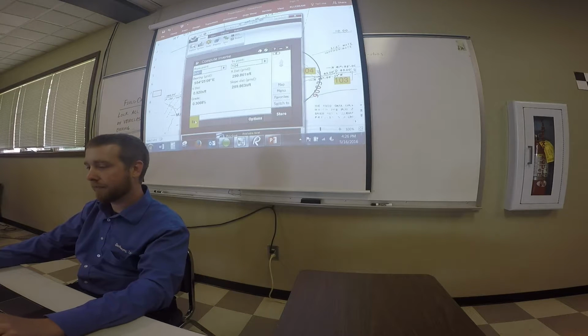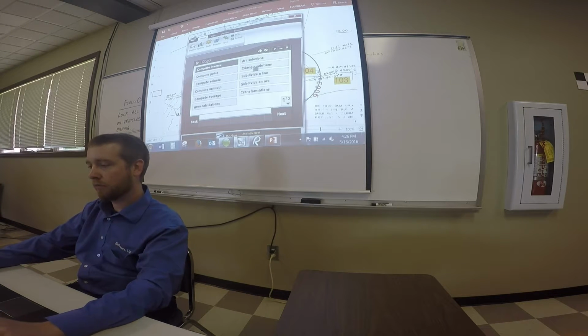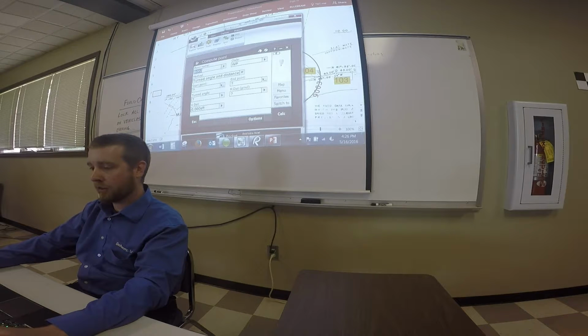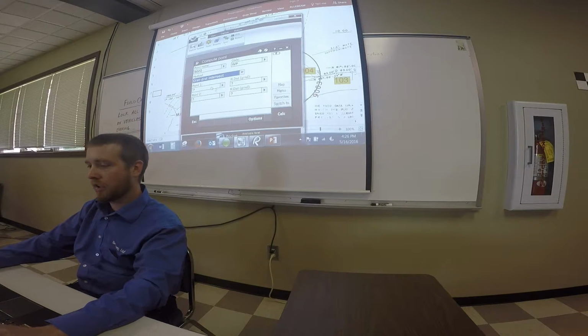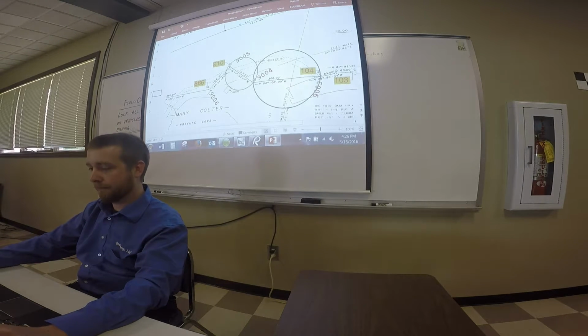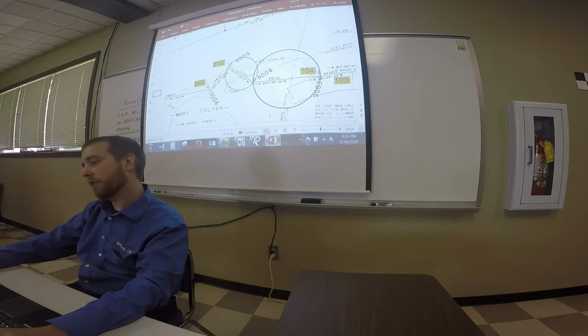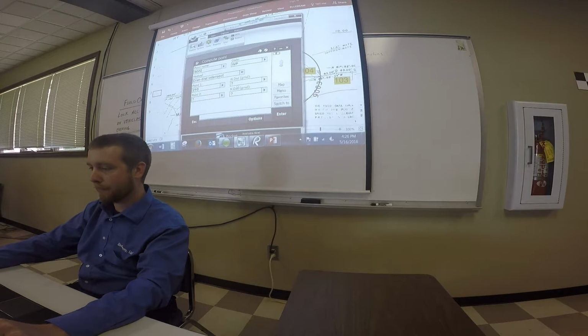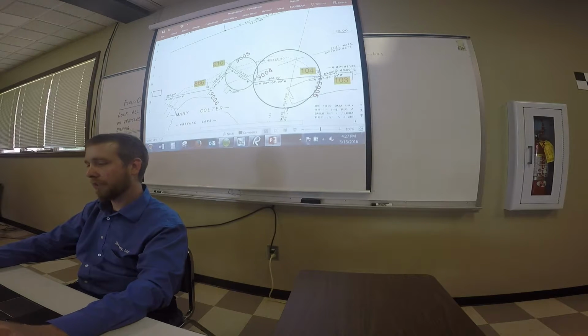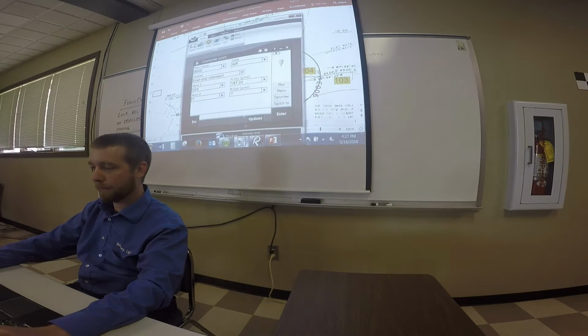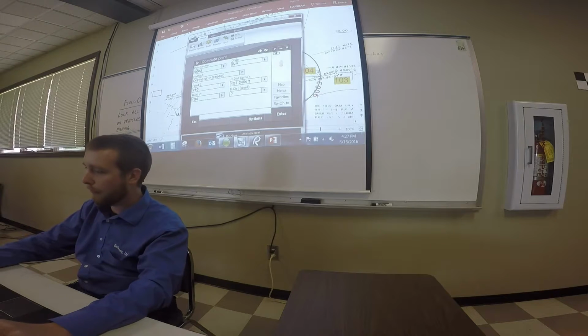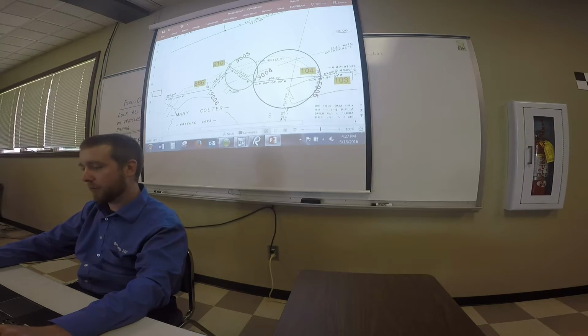So go into the data collector, go to COGO, compute point, and this time we're going to change to distance intersection. Point number 1, we'll call that point 210. Then coming off at 210, we want to come 157.24 feet. Right? That's going to be our first leg, our first circle. Then our second one, second distance, is coming off of point 104. And our distance is 300 feet, according to the plat.